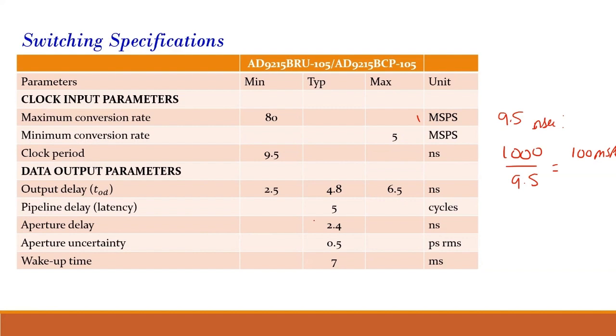See over here, they have the delay. 5 cycles is the pipeline delay shown. And this is a wake up time. It will take approximately 7 milliseconds for the ADC to power on everything. So those things also you have to consider when you're doing your hardware.